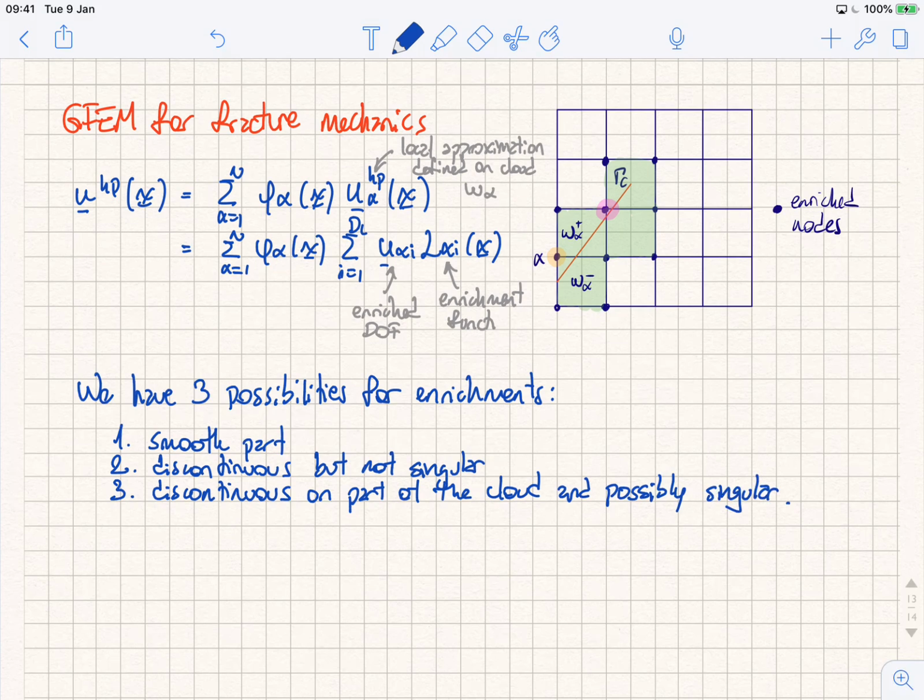So one of the interesting characteristics of this problem is that there is a singularity at the crack tip. So linear elastic fracture mechanics tells you that as you approach the crack tip, your stress goes to infinity. Of course, that doesn't happen in reality because normally we do not have a sharp crack tip, right? You don't have a crack that is so sharp that it has a zero length error, and besides, our materials have a finite strength. So that is never the case. But the theory predicts that there is a singularity at that location.